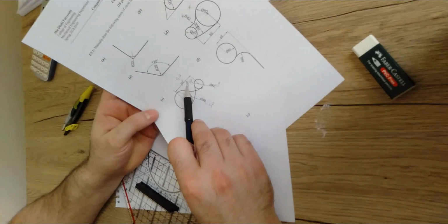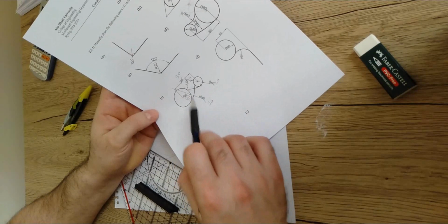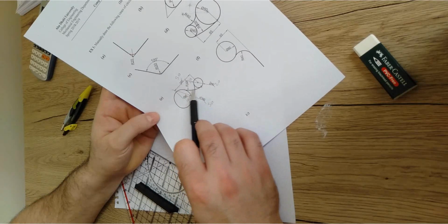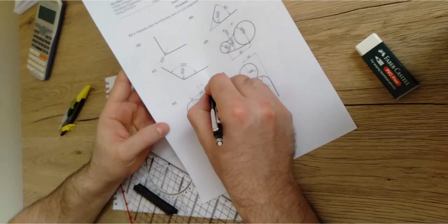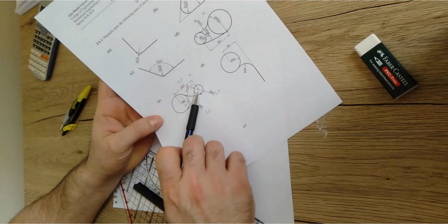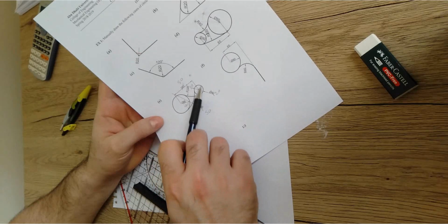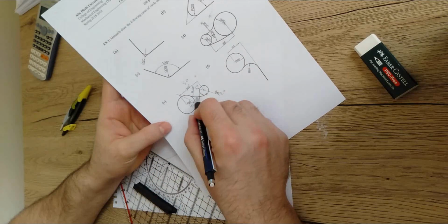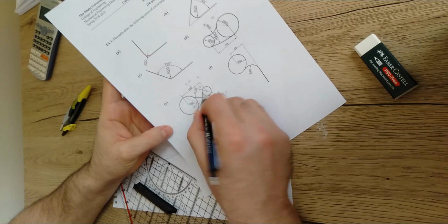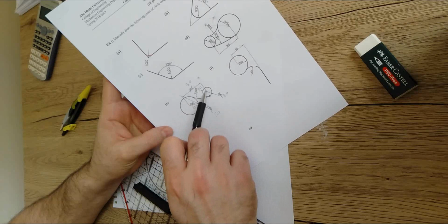Let us start with this first curve, which is radius 50. These two tangent curves both have the same radius. So the radius 50 of this curve, if I ask you where the center point should be, it should be somewhere above here, right? Then if I ask you to move from the center to the center of the small circle, are you gonna go over the tangent point of this curve to the small circle? No. Why? Because the tangent point of this curve to the small circle is down here. And we will not pass over this tangent point.